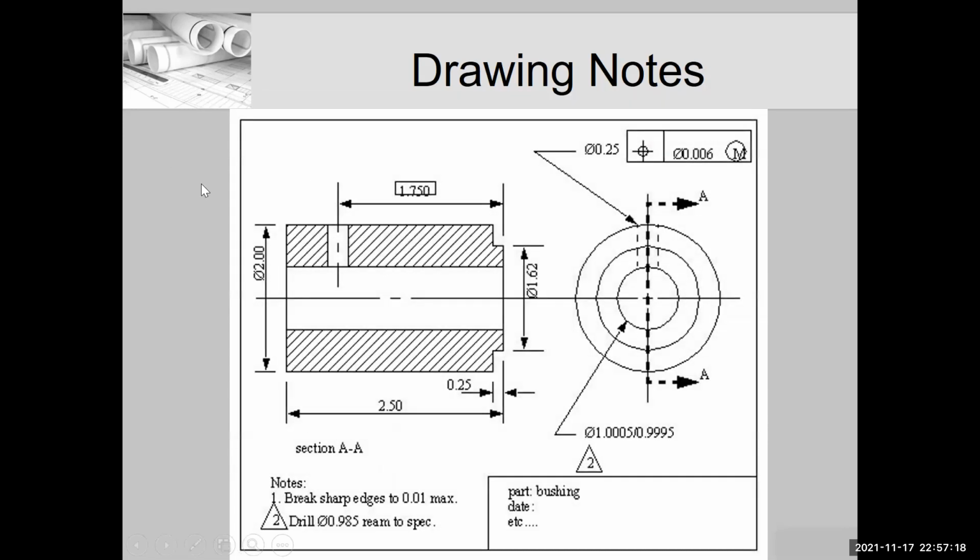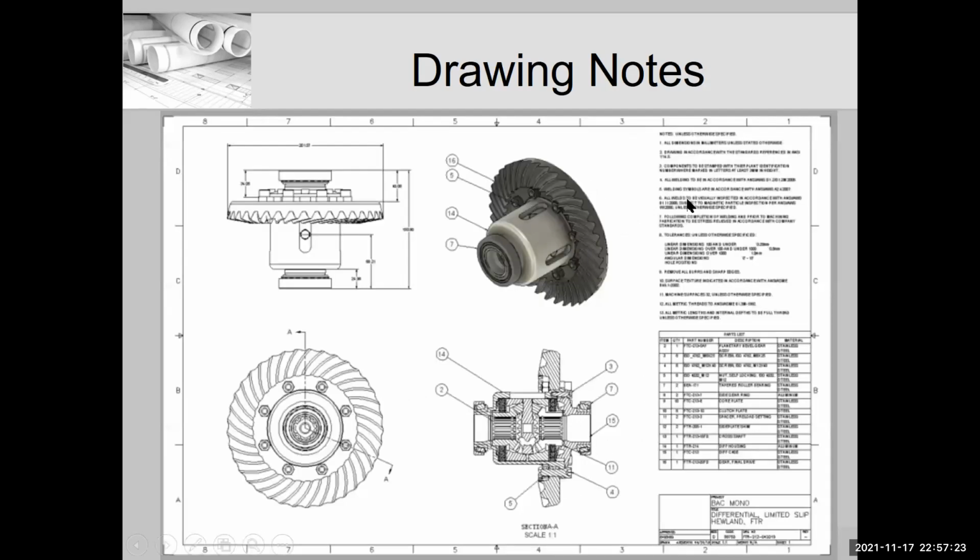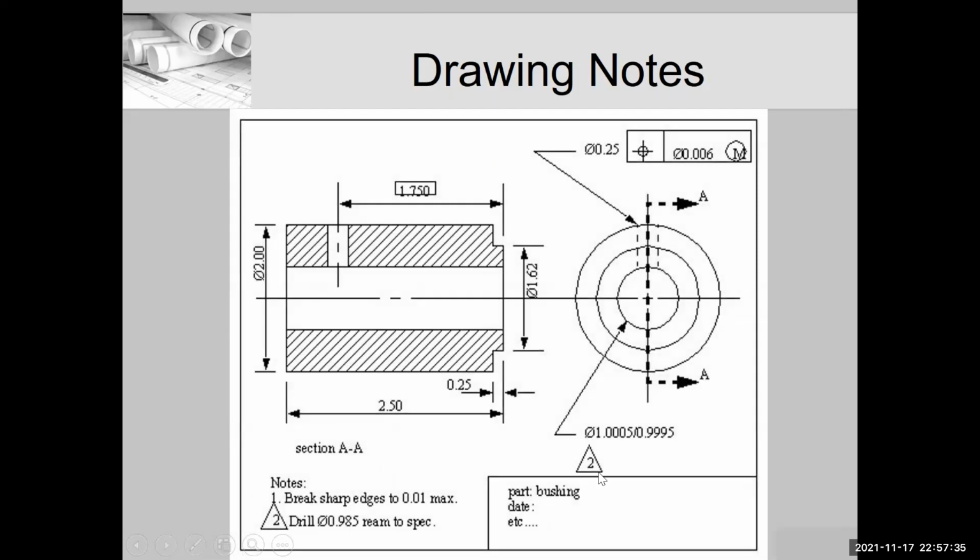Okay, another, here's a detail drawing, okay? And now, these are notes to the overall drawing, so it says here, unless otherwise specified. Okay, there's nothing else otherwise specified here. This note here in the little triangle with the number in it is specific to this diameter here, not to the overall piece, just to that one part of it. In that case, it is put in an up triangle like you see here with a number, and that is included in our notes section.